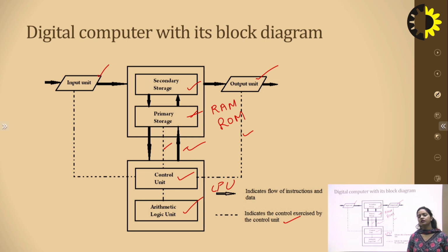In a hardware control unit, we have logic gates organized to decode the instruction and to execute the instruction in a further stage. Whereas in a microprogram control unit, we have a microprogram control chip, which is a programmed chip used to generate the control signals, right? Reading controls, writing controls from this control unit.